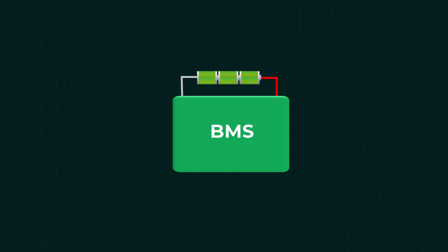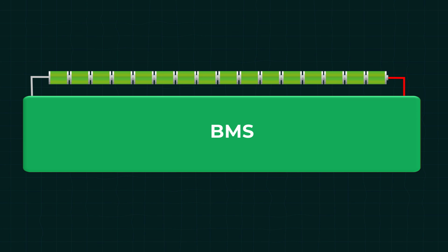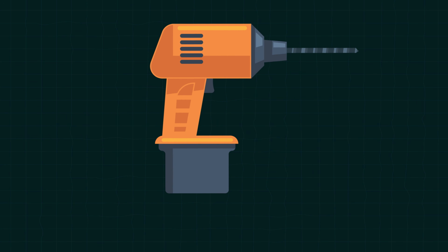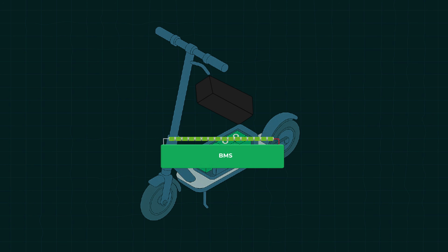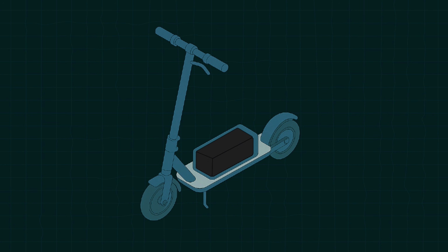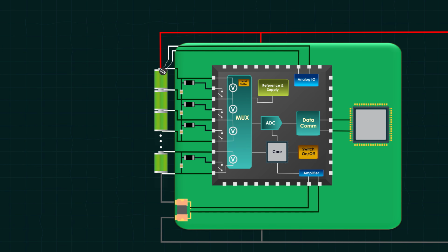There are multiple AFEs that are specifically made for up to 3 cells or 15 cell battery packs, perfect for things like power tools, typically for an 18-volt pack, through e-bikes of a 48-volt system. Instead of a tangle of discrete components, one of these AFE chips provides a one-stop solution.